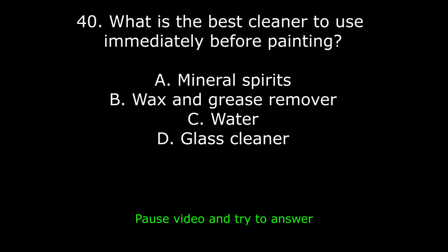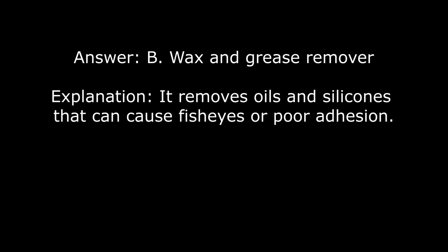40. What is the best cleaner to use immediately before painting? A. Mineral spirits. B. Wax and grease remover. C. Water. D. Glass cleaner. Answer B. Wax and grease remover. Explanation. It removes oils and silicones that can cause fisheyes or poor adhesion.